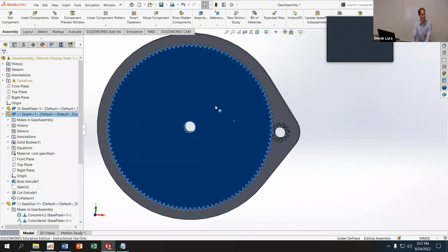Once you get to ratios that are that high, you're probably looking at using a combination of gears, right? If I want a 9-to-1 ratio, I can use two 3-to-1s and probably have about the same efficiency as a 9-to-1. Once you get higher than that, you're definitely going to be more efficient using multiple gear sets than using a single gear set. Maintaining the appropriate contact is difficult once those differences get very, very large.